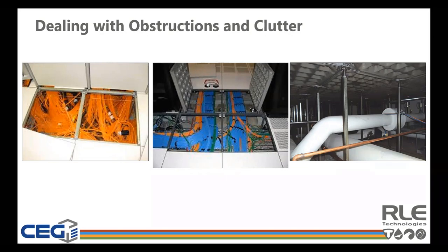And it just had a poor design. It had large chilled water pipes running directly in front of every cooling unit in the room. So this obviously restricted airflow and caused a lot of cooling problems for this particular customer. And the problem was so severe and impeded the cooling ability of the CRAC unit so much that the customer actually decided to move the chilled water pipes from under the floor to overhead around the perimeter of the room. And as you can imagine, in a live data center, this was an extremely large and expensive undertaking.